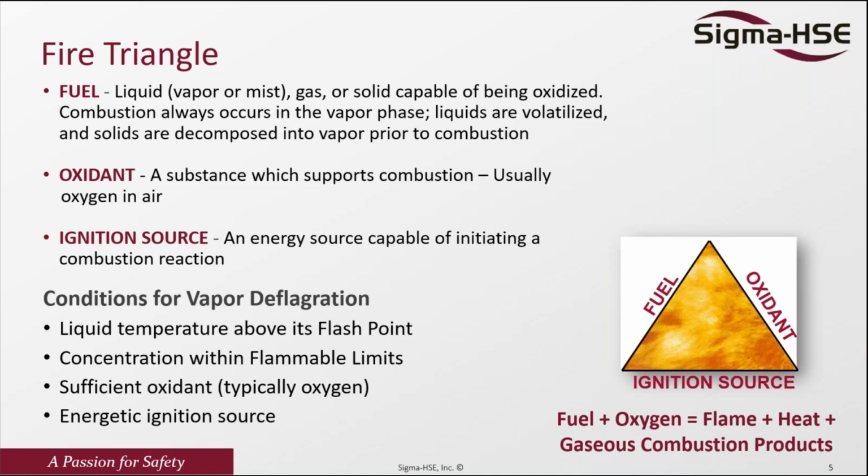So knowing this fire triangle, we need to understand, in case I have a solvent, how does this solvent ignite? There are some key parameters that we need to understand. First of all, with a pool of solvent, if you apply heat or something like that, it's not just going to ignite. It needs to form a vapor at the surface of the solvent.